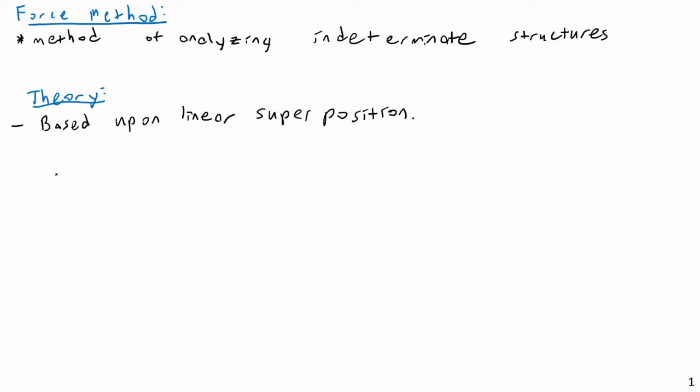to find equivalent systems, or to turn an indeterminate system into a redundant system. So the basic idea here, or perhaps the big idea I might say, is that an indeterminate system is a superposition of multiple determinate systems. Sorry, not redundant systems, multiple determinate systems.